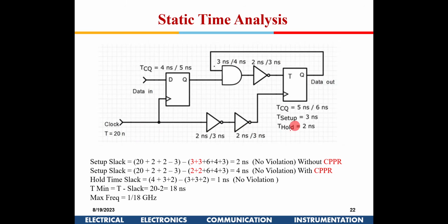Now let's take this particular example out here, right? So I have a clock coming here, right, for the setup. Okay, 20 nanosecond, right? So this is the first clock. So this data is going from here to here, 5 nanosecond, right?